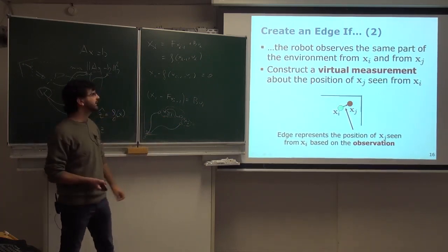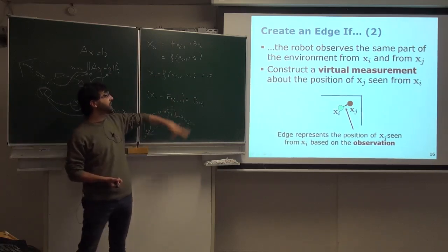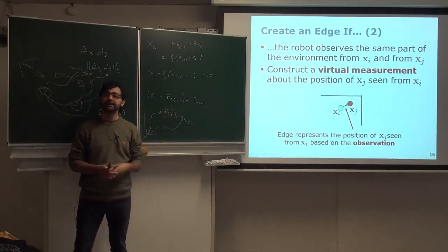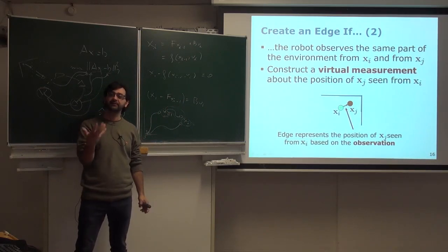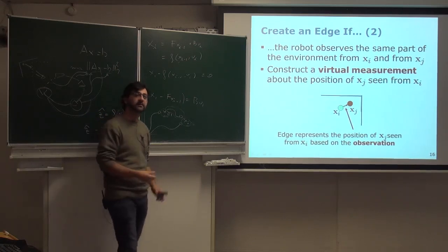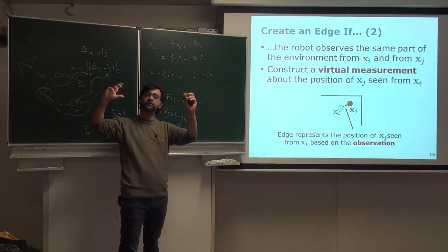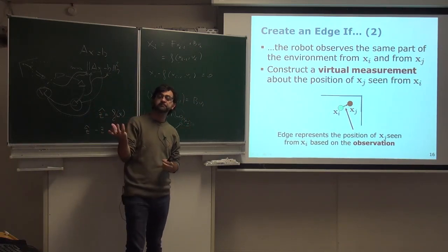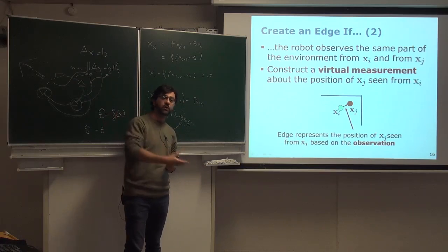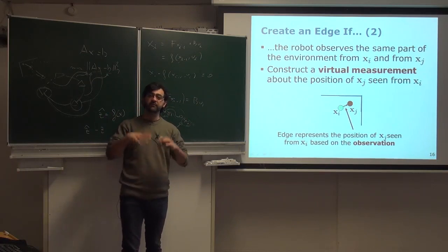So the idea here is that if we consider both the motion model and a scan matching, or an alignment between poses, as the same kind of measurement, as relative measurements between two poses where the robot was at some point in time, we actually do not need to make any distinction between the motion model, the observation model, and where this transformation comes from.